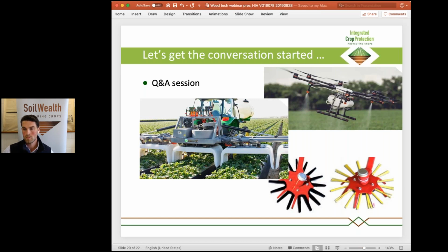Farmers were telling me that the repeatability is the issue with GPS-based systems. So I'm a member of the International Soil Tillage Research Organisation, and they looked into GPS RTK systems, and they were saying that even if you put all 3 satellite systems into one receiver and had the ground-based station, you still won't get the accuracy and repeatability required for high-speed mechanical weeding.